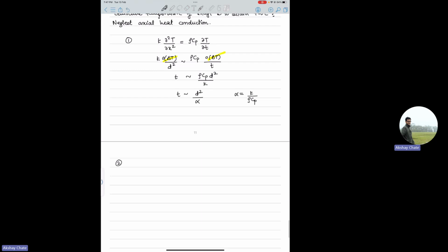The second thing is, let's say you don't know this scaling way. If you know the Fourier number, then also you can do it, because that is the only time connecting parameter, right? Since the initial temperature is the same and the material is different, the only thing we can conclude is that the Fourier number should be equal.